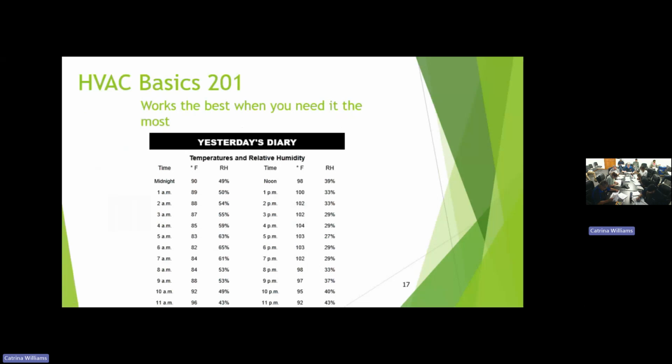I come up with 73 degrees. It's slightly more accurate than you can read, but that's how I determined it. So if you have the dry bulb and humidity, you get the wet bulb. Anybody need a little assistance following along? These are hard to read. They are hard, I agree.